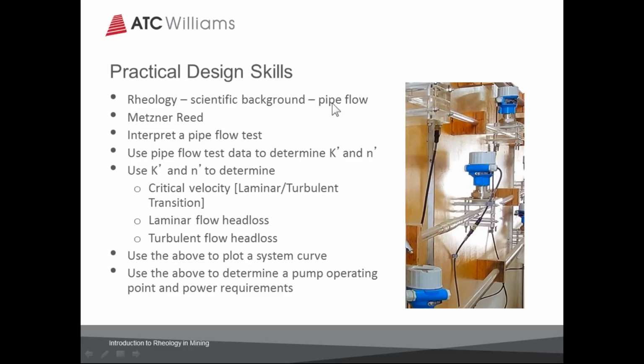Rheology, we're going to be talking about mainly in connection with pipe flow. And one of the most important and largely used design approaches for tailings pipelines, and any pipelines using rheologically interesting materials, was developed by Metzner and Reed.